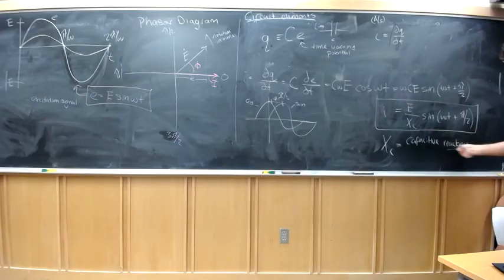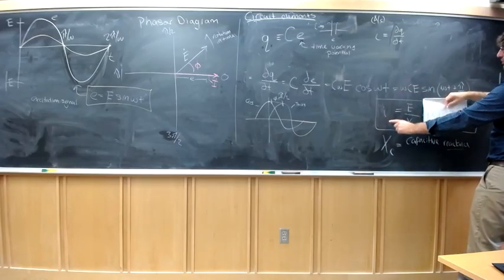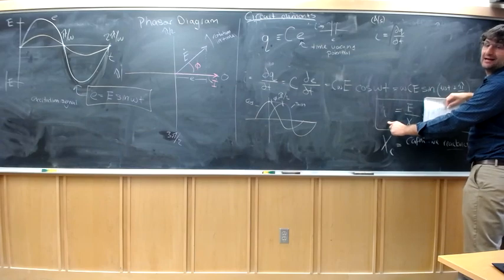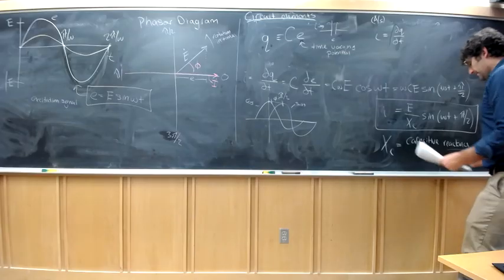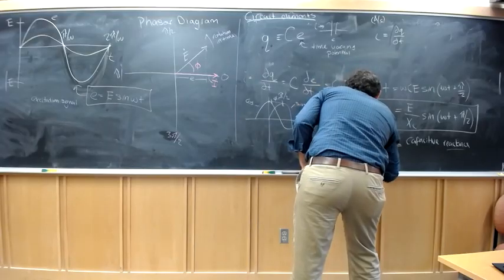So this is kind of like a resistance for a capacitive AC circuit. Right? Because what does this term go to? Its maximum. The sine term, 1. So that looks a lot like Ohm's law, right? So it's kind of Ohm's law for a capacitor under an AC excitation. And XC here, capacitive reactance, is defined as 1 over omega C.